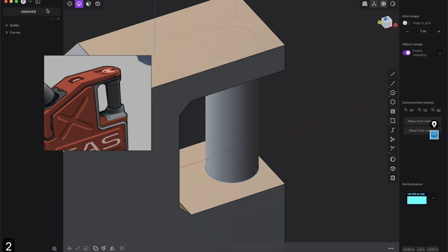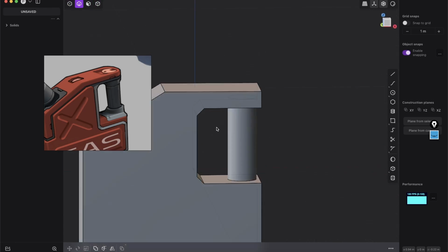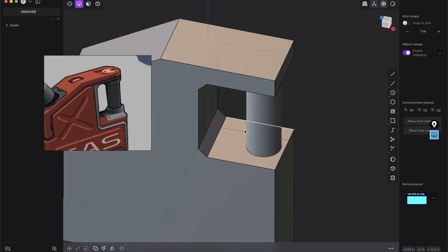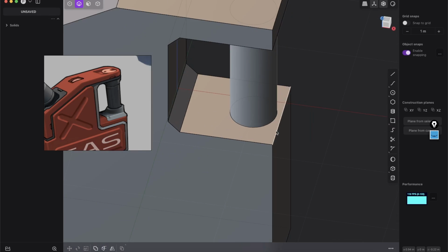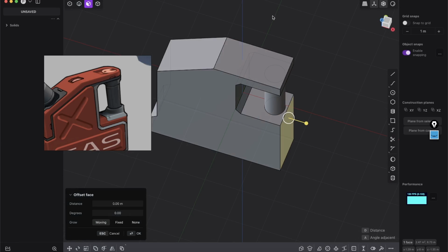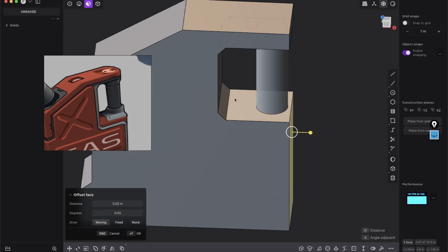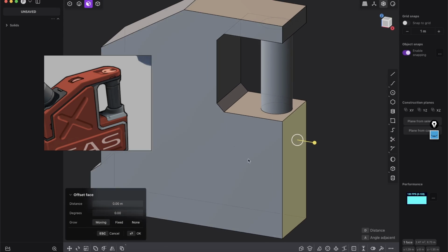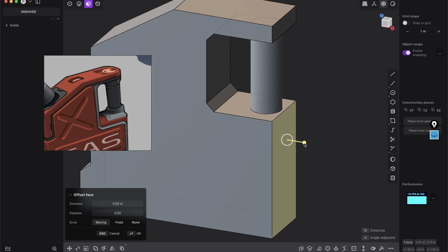Press 2 for curve or edge mode. So with edge mode, you can select curves and just delete this edge or curve here. Perfect. So now just in this example, I want to press 3 again and select this face. And by the way, I don't want to see this grid all the time. So you can just click on toggle overlays, and then you don't see the grid. I don't know, I just like to work this way. And so this face is selected. Let's extrude this a little bit.